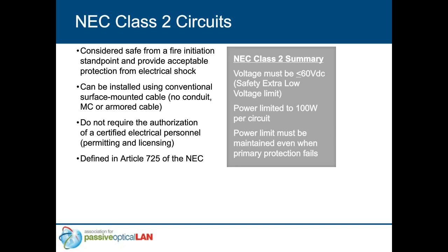However, the standard requires you to meet that even when the fuse, which is the primary protection device, has failed and is not operating correctly. And you cannot guarantee then that you'll meet a 100-watt limit. So consequently, fuse panels aren't really available for use in Class 2 circuits, although some have been installed simply because people were not totally aware of the NEC.